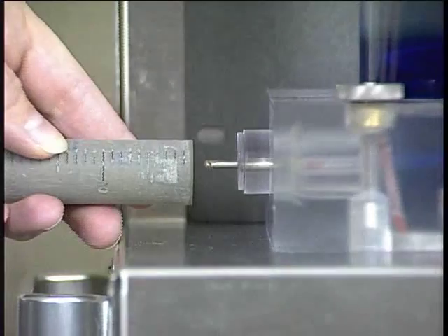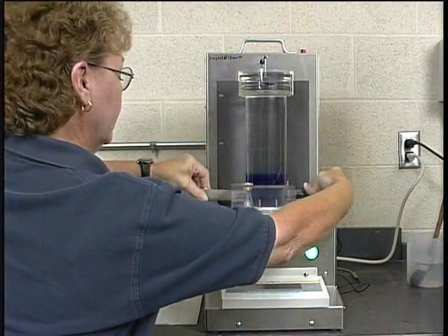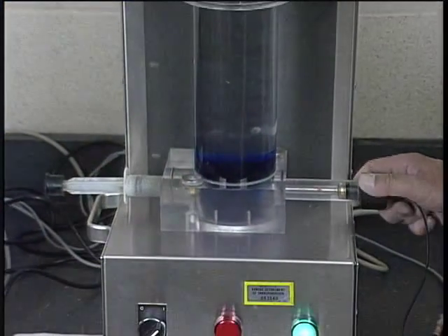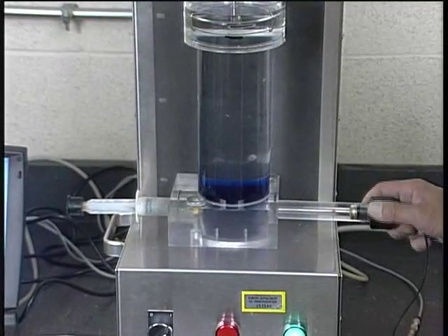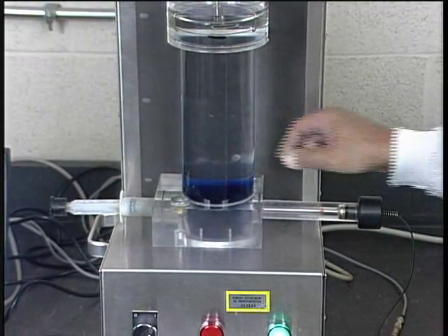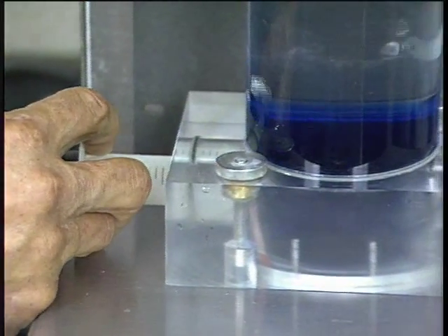The sample of mortar in the syringe is placed on the end of a plexiglass rod that also contains a temperature probe. The combination is positioned with the end of the syringe at the edge of the cylinder. The plexiglass rod is drawn back to the other edge of the cylinder. The sample is then injected into the glycerol at the bottom of the cylinder.